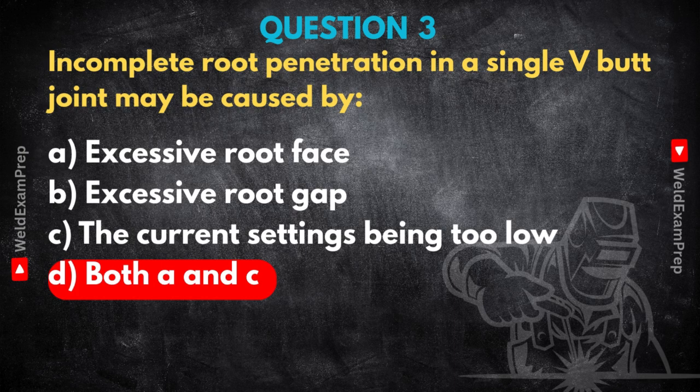As we discussed, that typically leads the other way towards burn-through, not incomplete penetration. Right, it goes too far, drops out. Yeah. This raises a really practical question, though. Given how similar incomplete fusion and incomplete penetration sound, how do inspectors quickly tell them apart in the field? Especially if you can't do destructive testing right away. What are the visual clues?